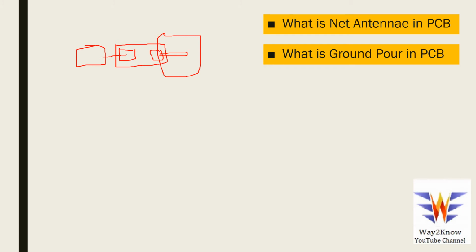Because we directly don't probe on the PCB. So when we put it live during our bench testing, we may not see an issue, but when it goes onto the field and is used, it might cause radiation and hence interference. So these kinds of open-ended traces should be eliminated.